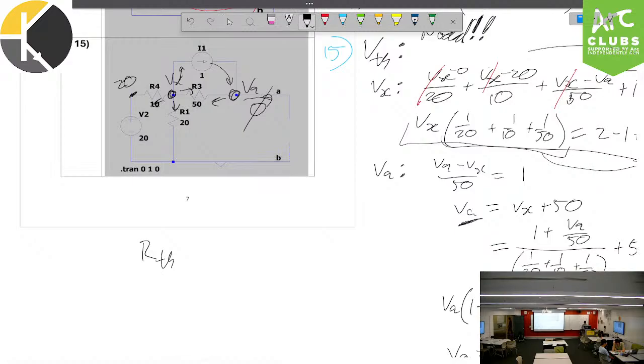So, our Thevenin, what do we get? Let's erase all the little scribbles I made on here and think about what we do. So, method 1, once again, turn off our sources. The current source, open circuits, the voltage source, short circuits, and once again, I look through, I get my 50 ohm.